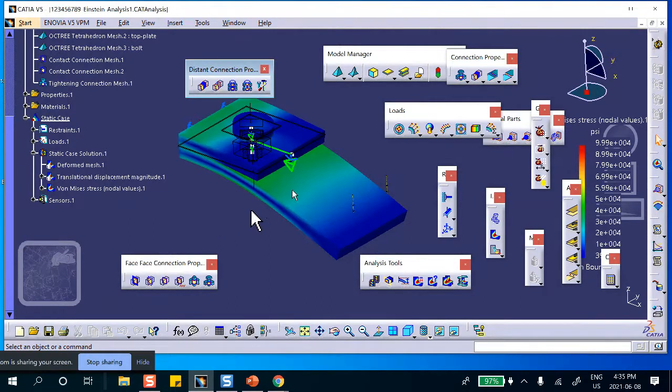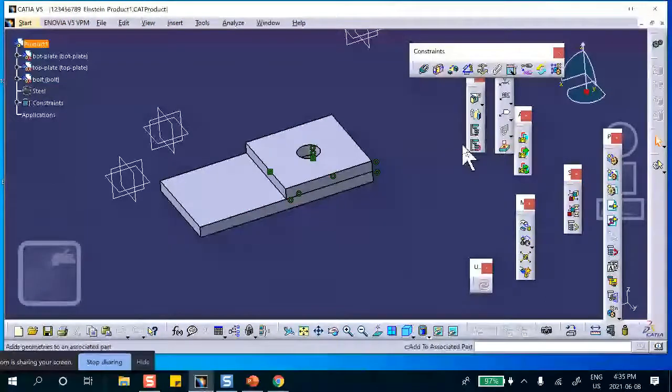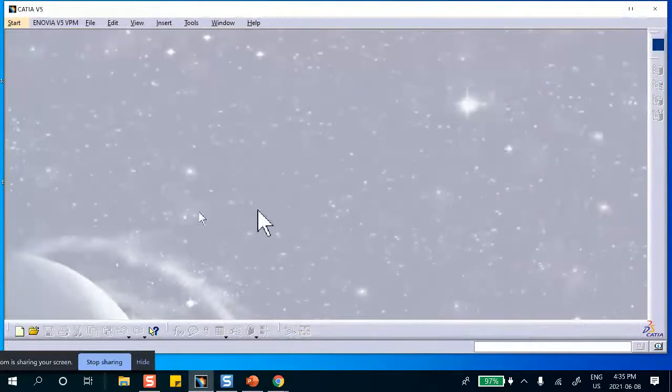Unnecessary. Because after all, when you put these plates together, you don't care about the bolt. All you want to make sure is that these are clamped together with a certain force because you want to load the structure. So there's something called a virtual bolt. Let me do the problem for you with a virtual bolt, where you do not actually model the bolts. So let me kill this. Okay, let me kill that.